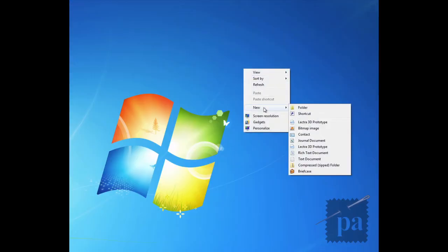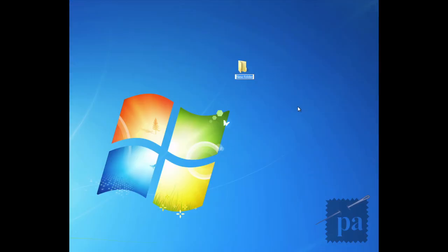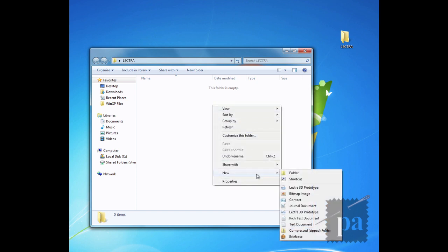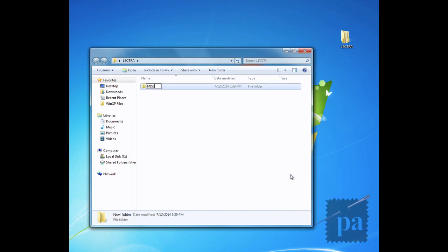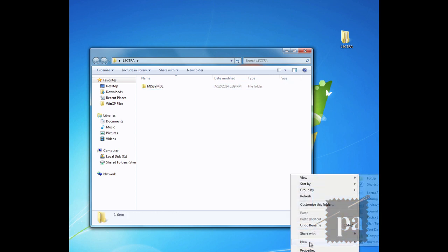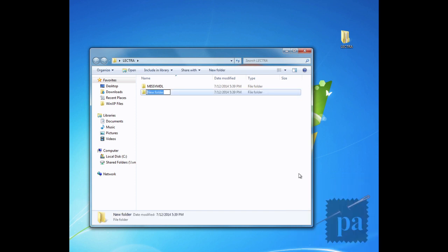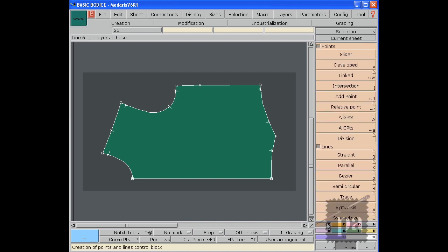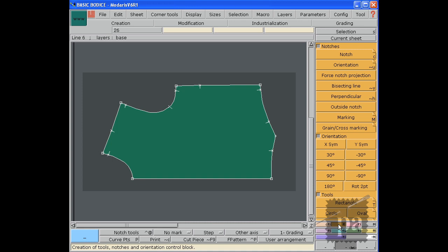Lastly, create a folder called Lectra, all caps. If you use a USB drive, do not create this folder, just simply create the following two folders under the root directory. Now, in Lectra, create two folders, Missy MDL and Missy PROD, all caps. Just a note, this system only reads caps, so if you use lowercase, you may have some problems. So just make sure anytime you type anything in here, you're going to use caps.